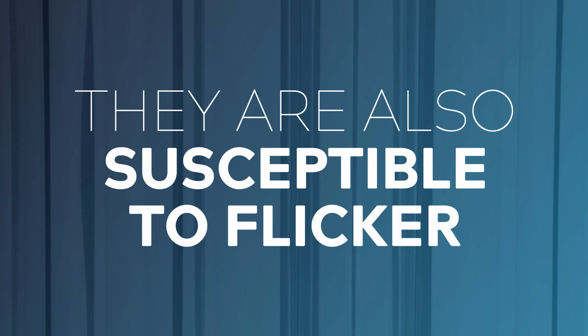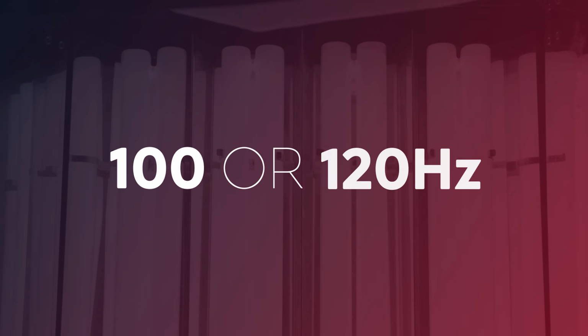You can also find bulbs in a variety of color temperatures, so you can get fluoro lights in tungsten, daylight, and in the middle at about 4500 Kelvin. Fluoros are also very susceptible to flicker. They have ballasts that operate at either 100 or 120 Hertz, depending on where you are in the world.